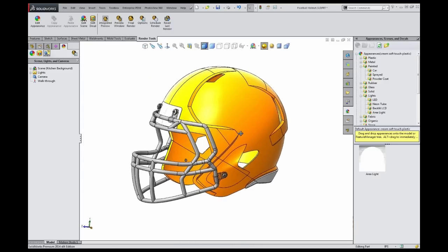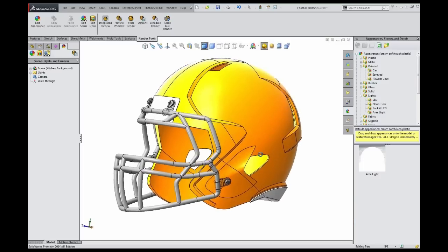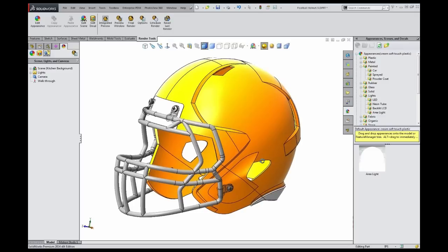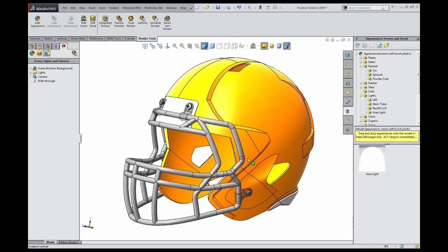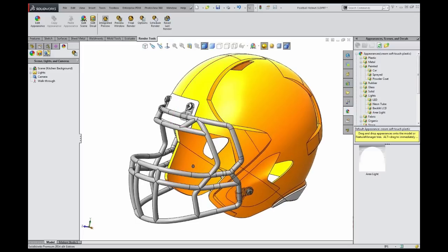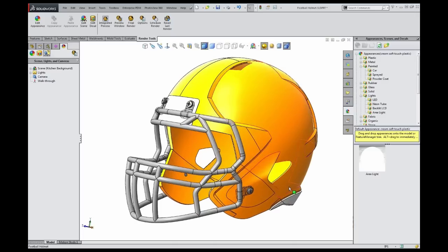And to position this model just right, the number one thing, we're talking about making a photorealistic rendering. There is absolutely a high degree of unrealism going on with this render right now. The reason is because I don't have perspective mode turned on. Everything in real life has a vanishing point, so perspective applied to it. So we cannot expect, especially with something with a bunch of parallel edges, if they all truly remain parallel from an isometric view, that's going to have a natural feeling to the viewer that it's a real photo, which is what we want to trick our viewers into thinking. So you got to apply perspective.